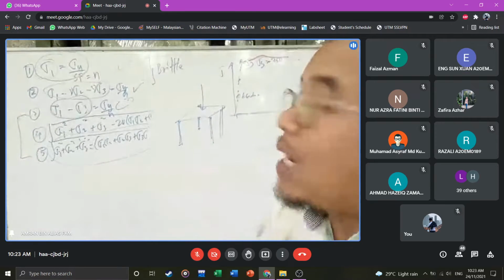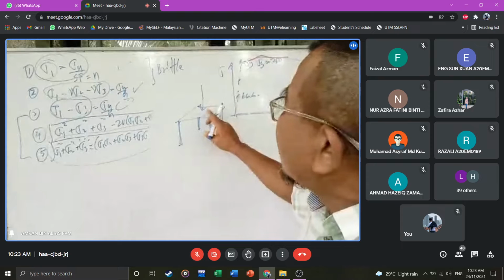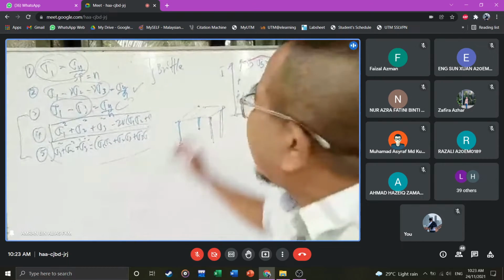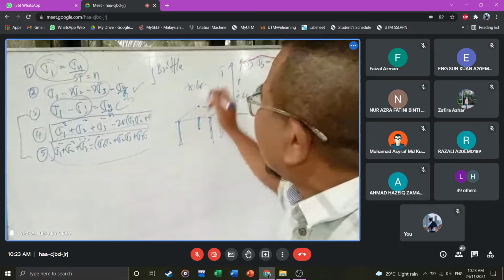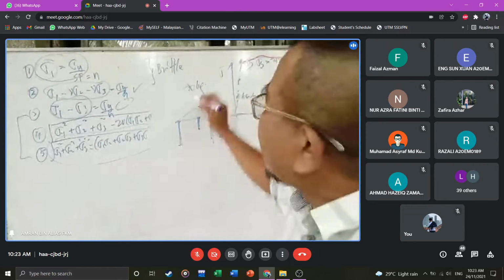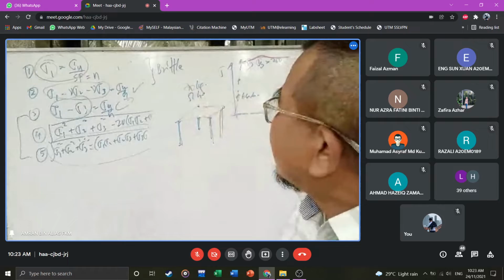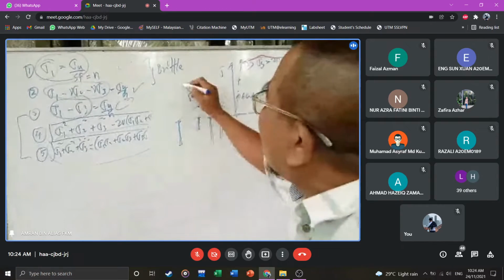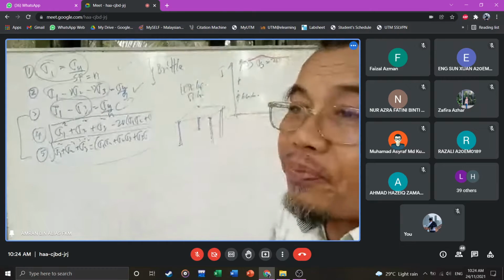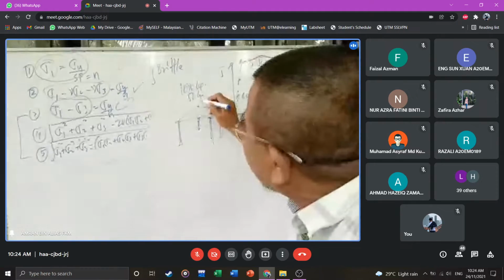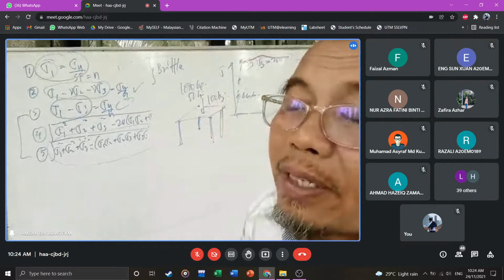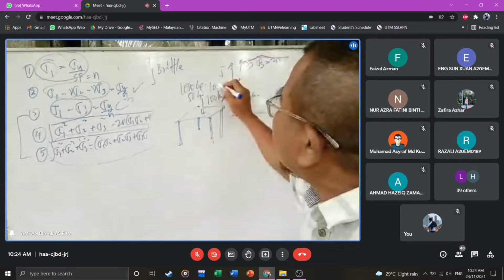So you sit. This is for the normal guy in the class, weight 70 kilograms. Maybe the girls weigh 50 kilograms. Maybe there's one or two guys who are quite big, the weight is 100 kilograms. So you design the load for a 100 kilogram person sitting there, or 1,000 Newton.